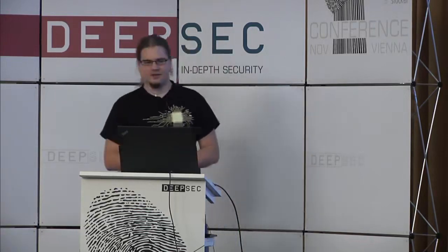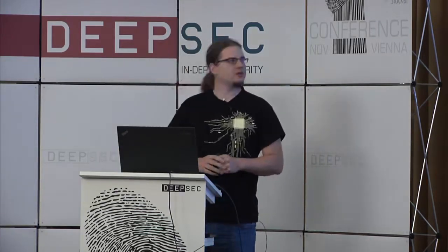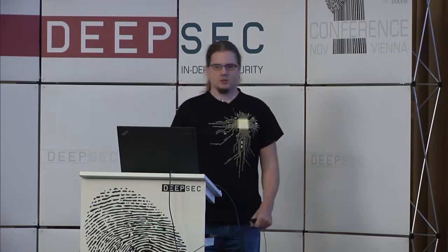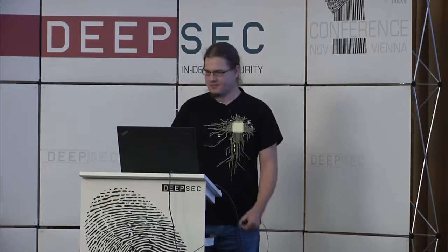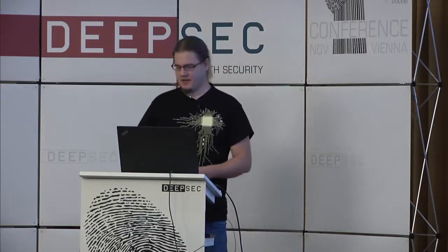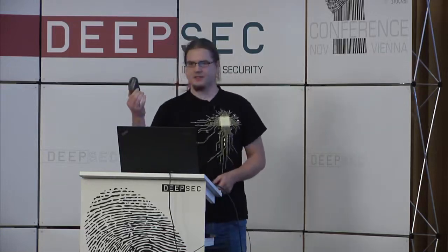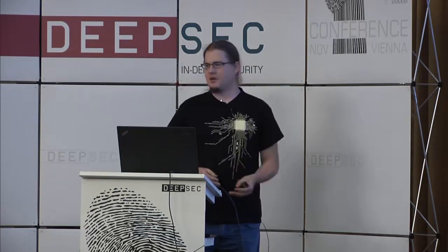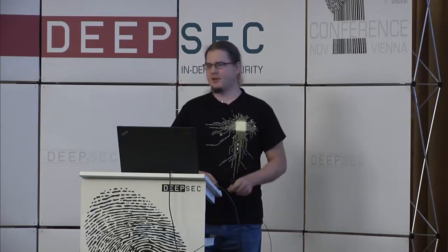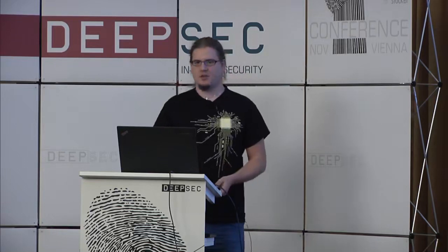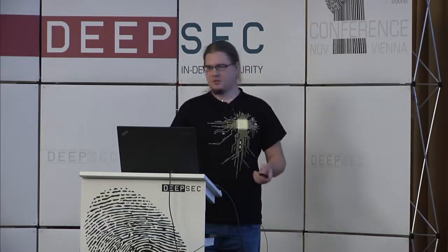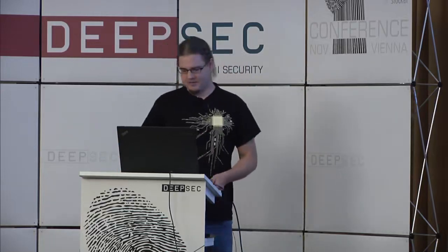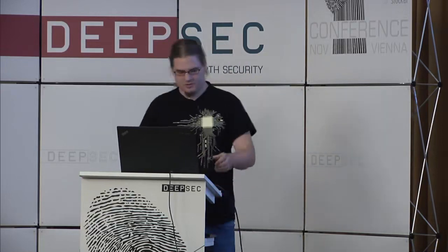That's everything I have about the readout protection, but let's talk about the next attack. The next attack was exploiting some really obvious stuff. The mice of that wireless desktop set, mice like this, are just unencrypted. So the keystrokes are encrypted, of course. Everybody could sniff your password while you're typing. But for the mice, the vendor said, well, that's not worth the effort. If you can see the mouse moving around, that's nothing harmful. Or if you can control the mouse, there's nothing really bad you can do with that either.